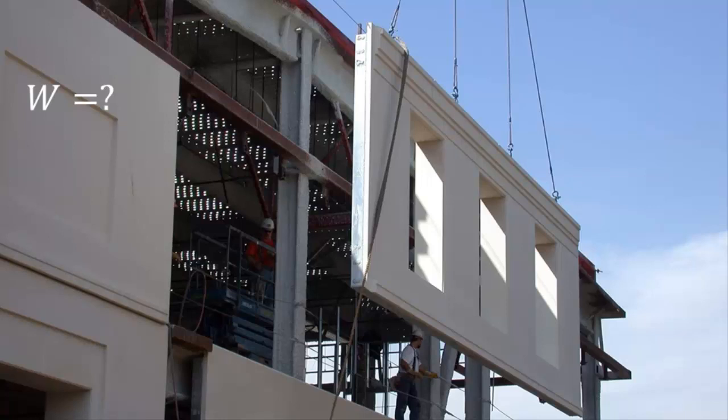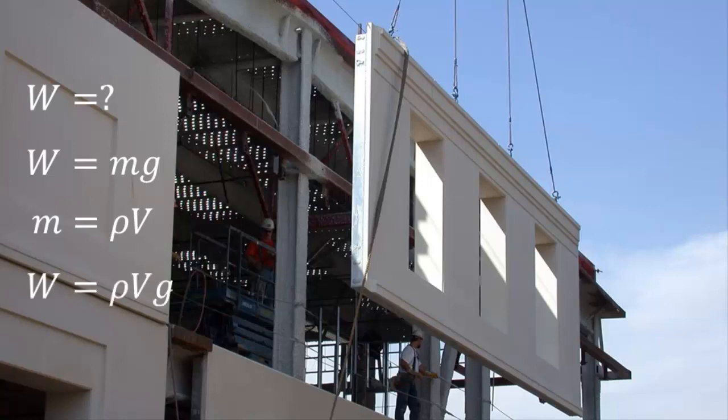It's not practical. But what you can do more easily is to measure its dimensions and calculate its volume. Then, knowing the density of the concrete based on its material properties, we can thus calculate its mass and therefore its weight. So knowing the density of various different construction materials is really important in being able to calculate the total load of the structure.